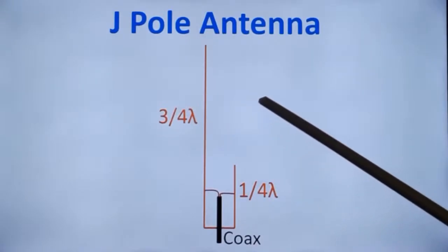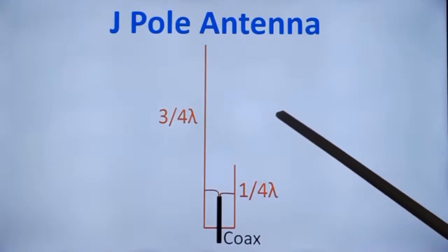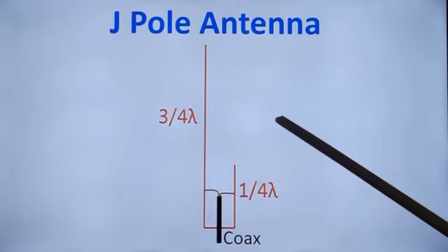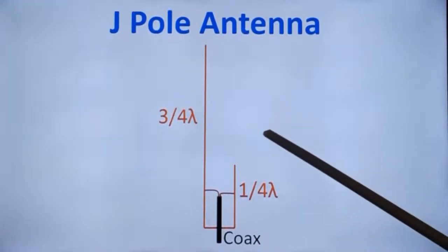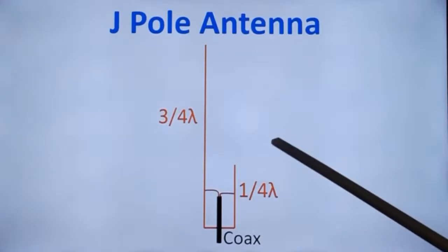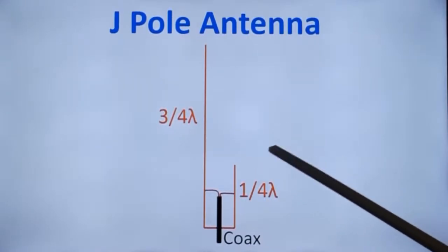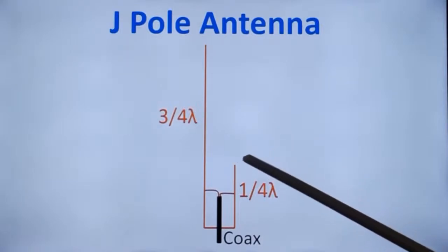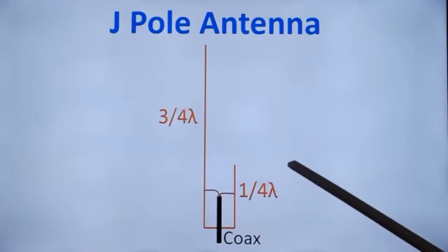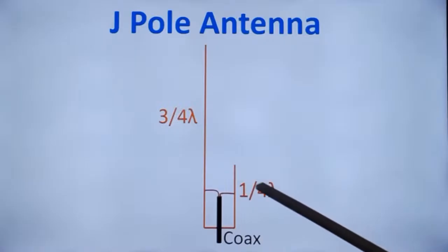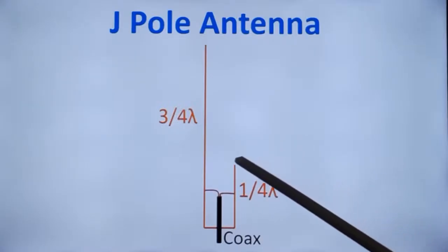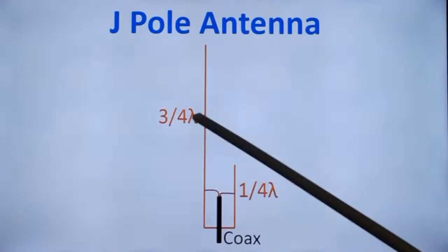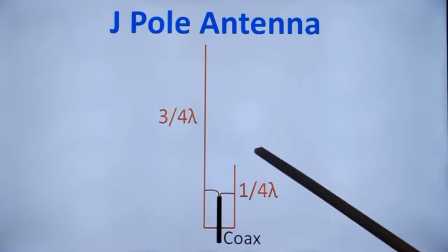This is just like you use a 7 megahertz dipole antenna for 21 megahertz also, with a reasonably good standing wave ratio or SWR. Similarly, this can work as a dual band antenna also, though not optimal. And it is also mentioned that when you use a 2 meter J-pole for 70 centimeter, the angle of radiation is not ideal for terrestrial repeaters or terrestrial communication, but it is okay for satellite communication.